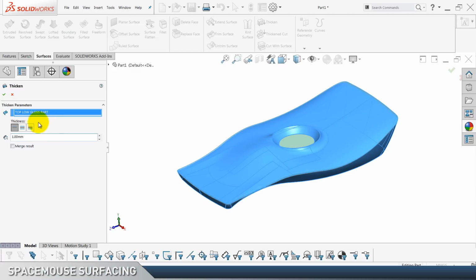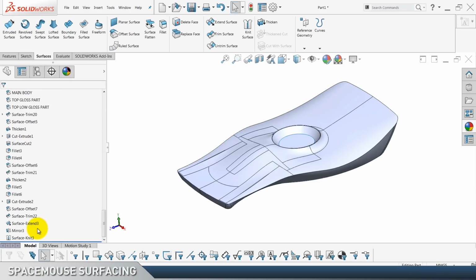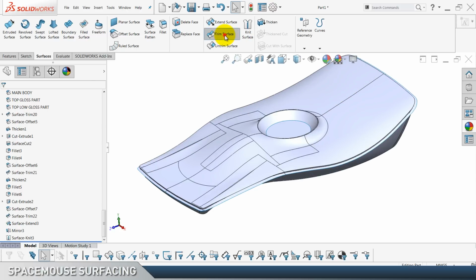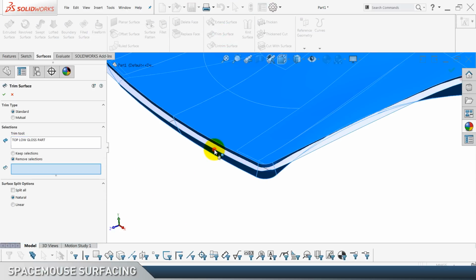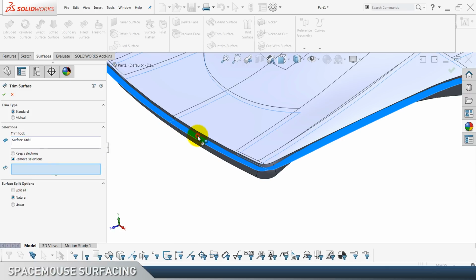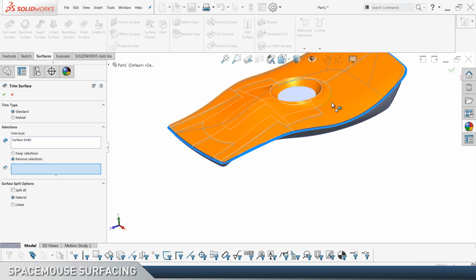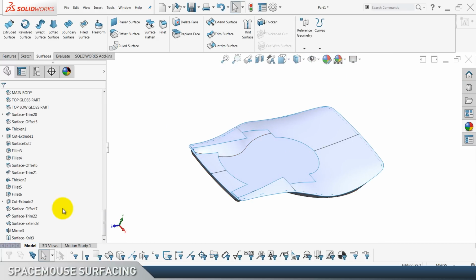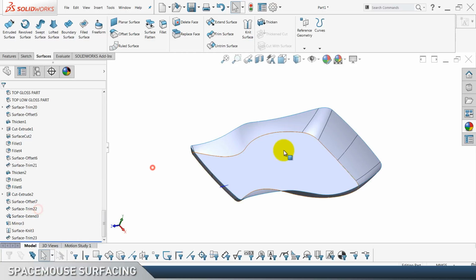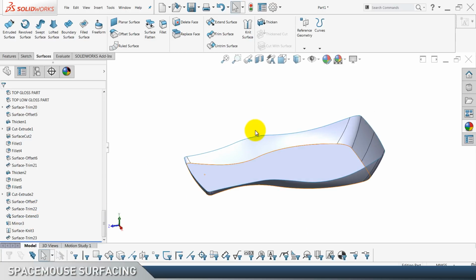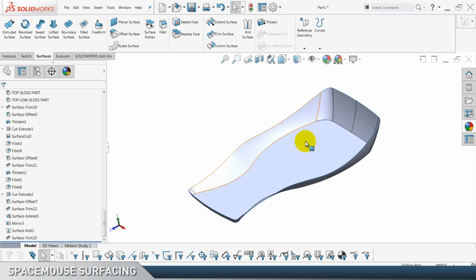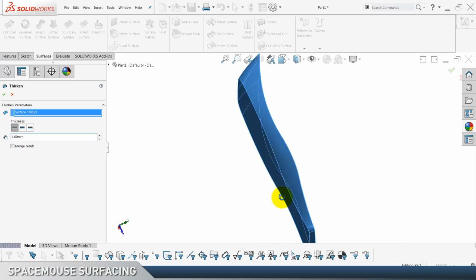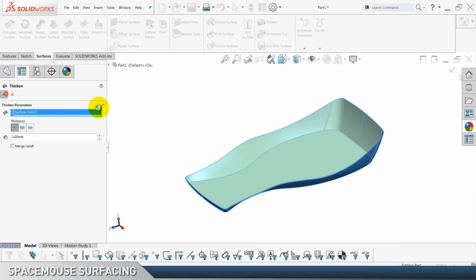No, we actually need to trim it out with this extended surface. So trim tool is gonna be this one, no, not that one, the offset, and remove this top piece. Okay, finally something is working fine. Hide surface extend, and this is what we want, this bottom part. Thickening for 1 millimeter to the inside. Click OK, and